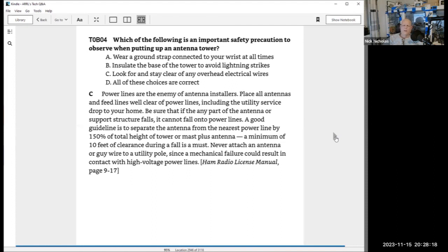No, it is not legal to strap a tower to your house. BOCA prohibits it. There are straps for attaching towers to buildings, but only non-residential buildings, like police departments, fire departments, and commercial buildings, provided nobody lives there.